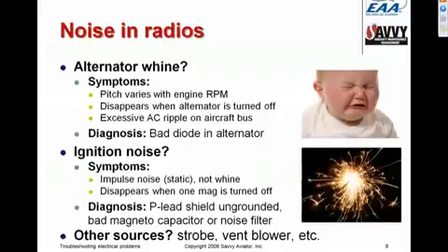The alternator whine is caused by excessive ripple on the aircraft bus. I'll show you a picture of that in just a moment. And it's virtually always caused by one or more rectifier diodes burning out in the alternator. And as we said, inadequate alternator cooling is frequently responsible for these diodes burning out prematurely.